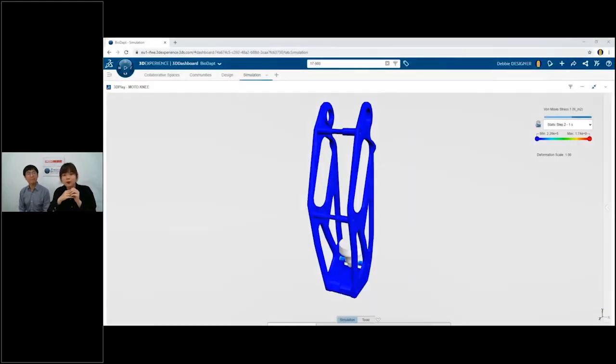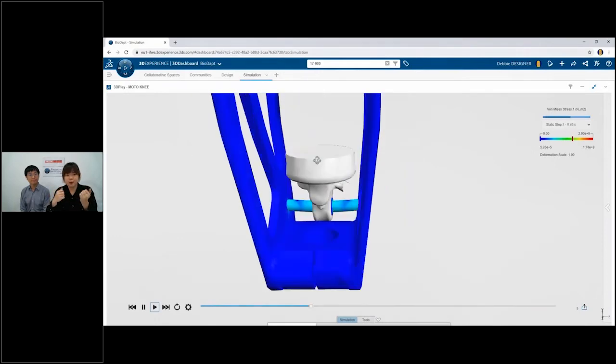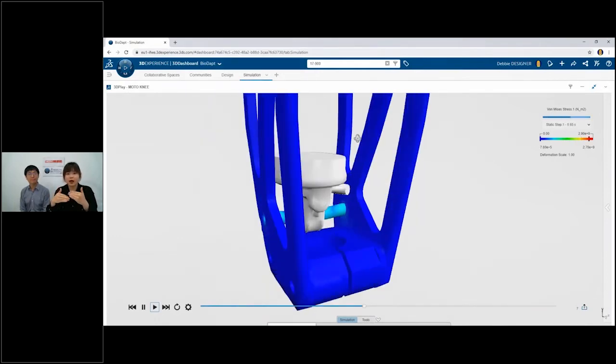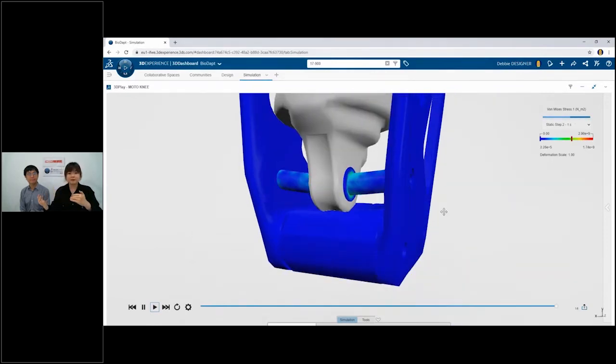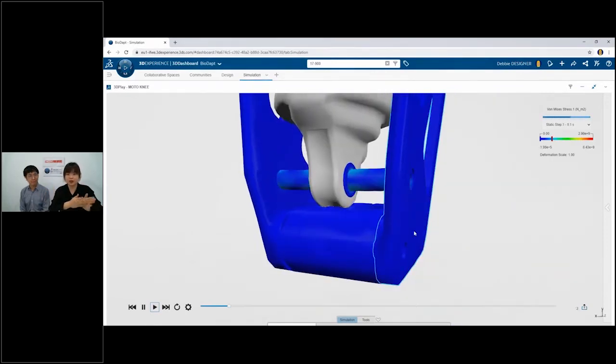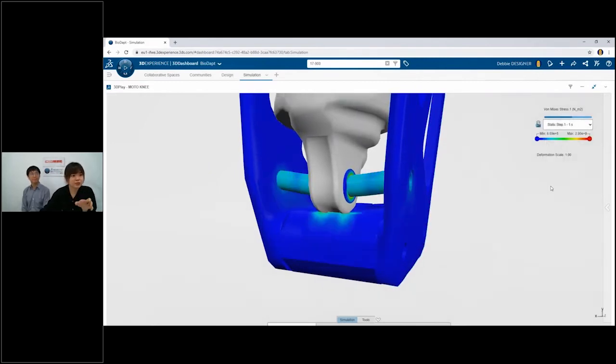Okay, so after I have uploaded my model into the SIMULIA website, Lee will be able to trace the changes in my model, and because everything is uploaded into my company dashboard, he can open the file share and run the simulations on the cloud. This is actually running on the cloud because this is the 3DEXPERIENCE platform. And in this simulation result, it shows that the lower bracket was pressing against the other parts when it moved. So he will then inform me that this part needs to be redesigned.